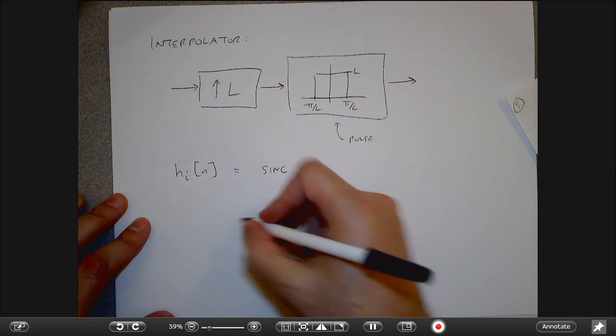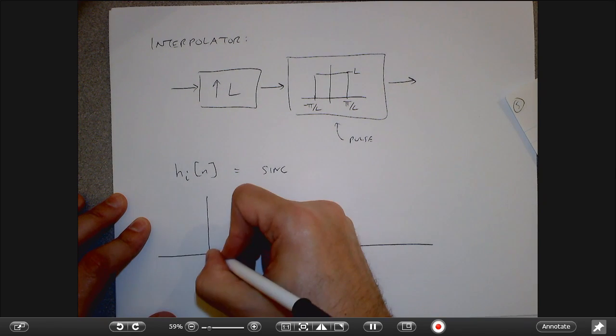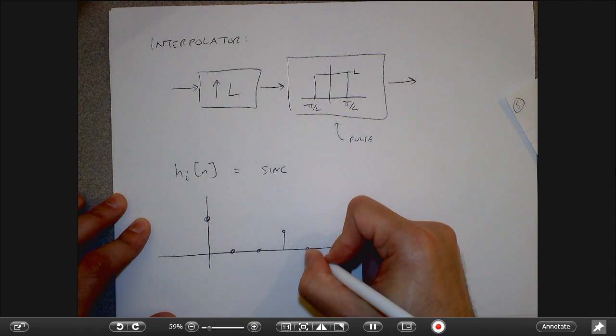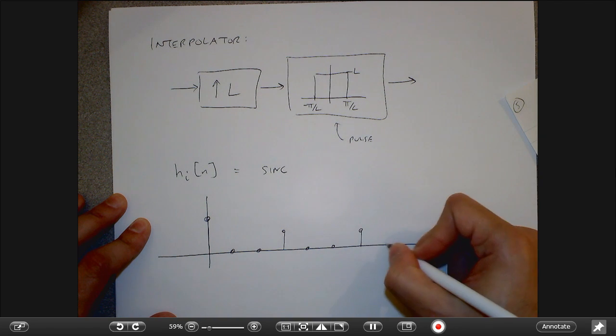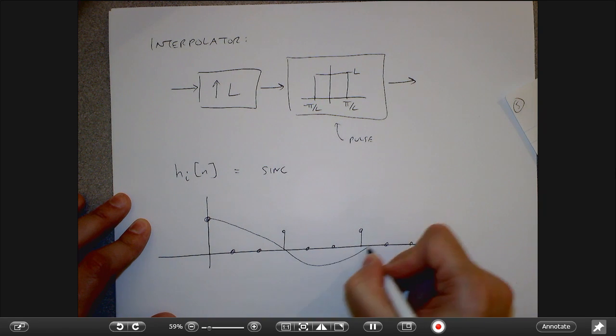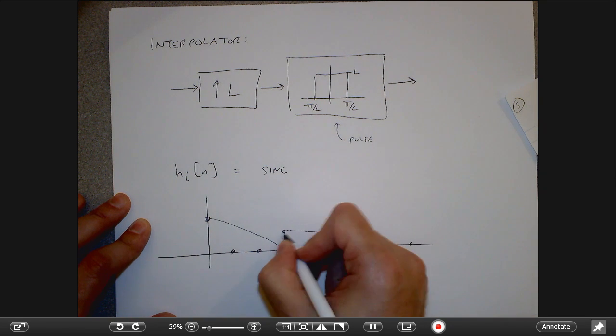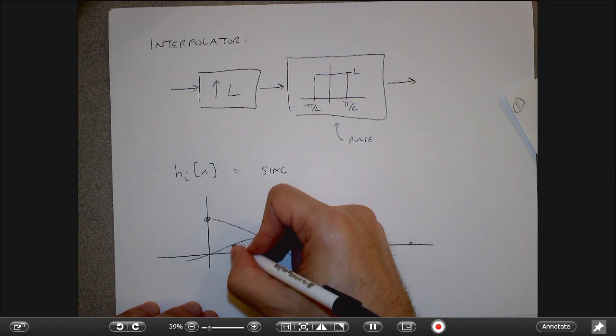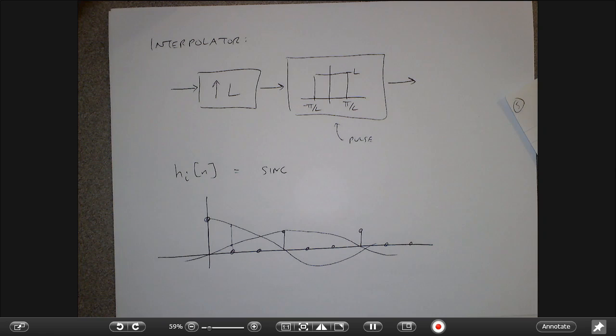And so fundamentally what I'm doing is taking the samples and adding up a bunch of sinc functions, thinking about these numbers as weights on them. And all these sinc functions will magically add up to the right thing in the middle samples, right? Because really this is nothing more than the kind of interpolation that we would normally do for reconstructing the signal.